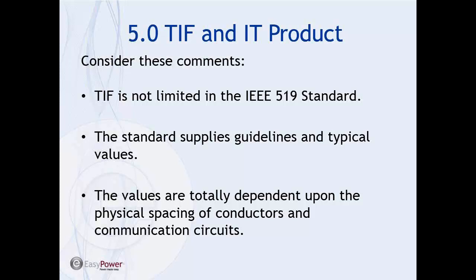We ended up putting capacitors strategically located on their distribution system until we got the value dropped. Unfortunately, we created a small resonance on the system too, so it was bizarre. We had higher fifth harmonic, and so we were actually exceeding IEEE 519 harmonic limits on the feeder, but we solved the communication circuit problem. So you can see how these things can go back and forth.